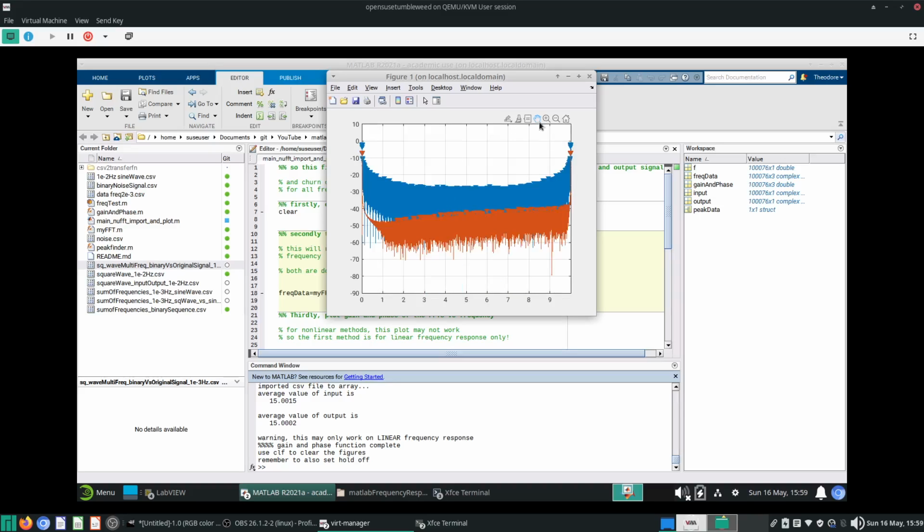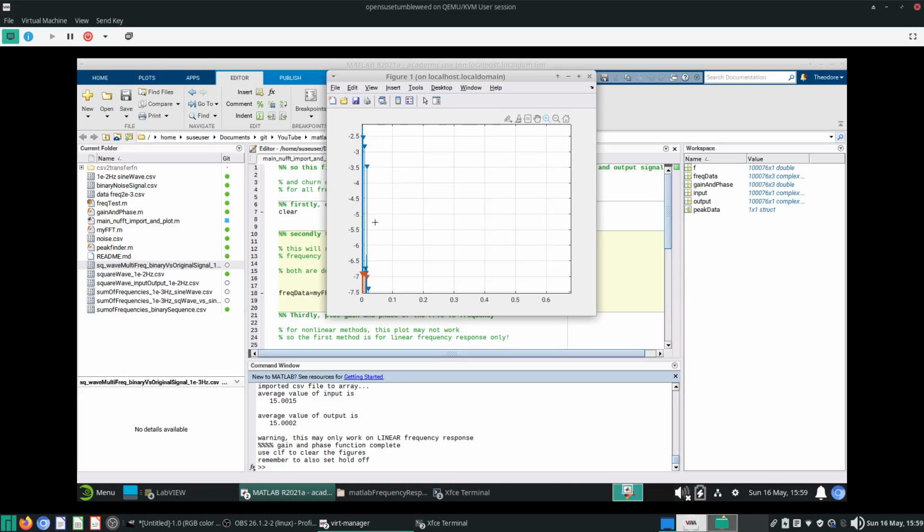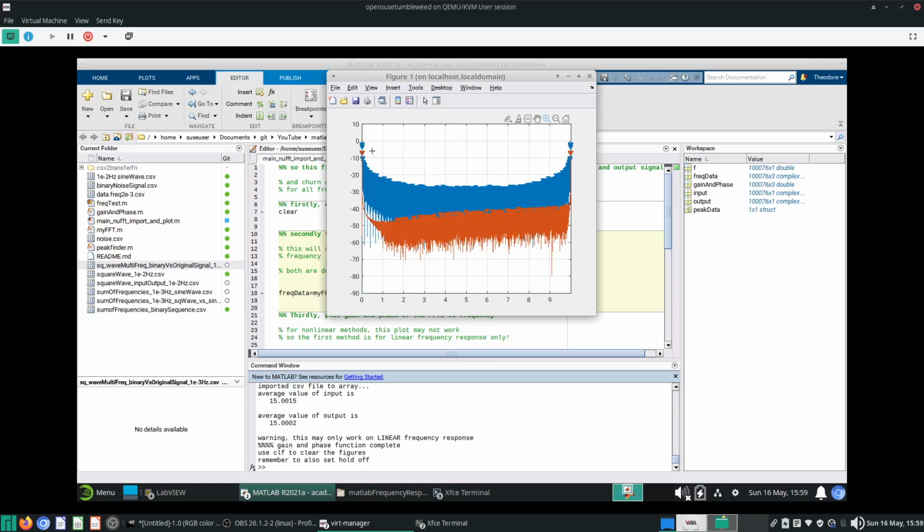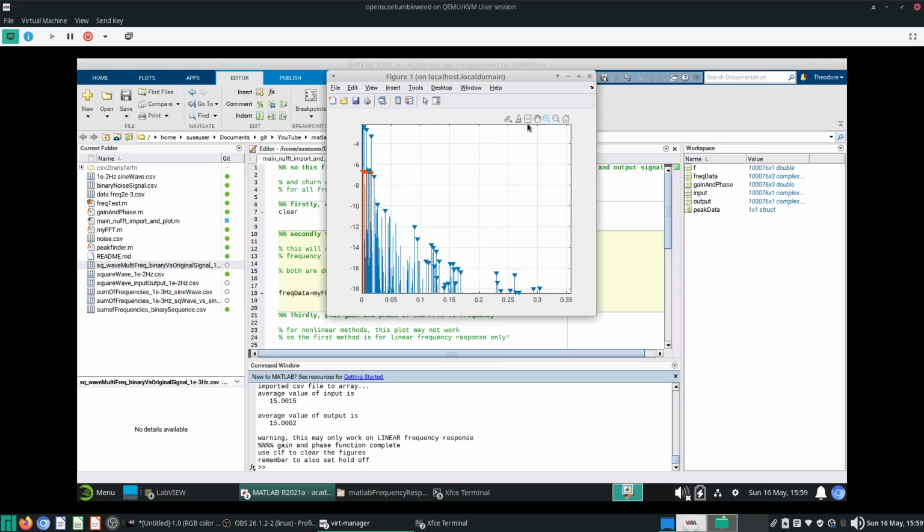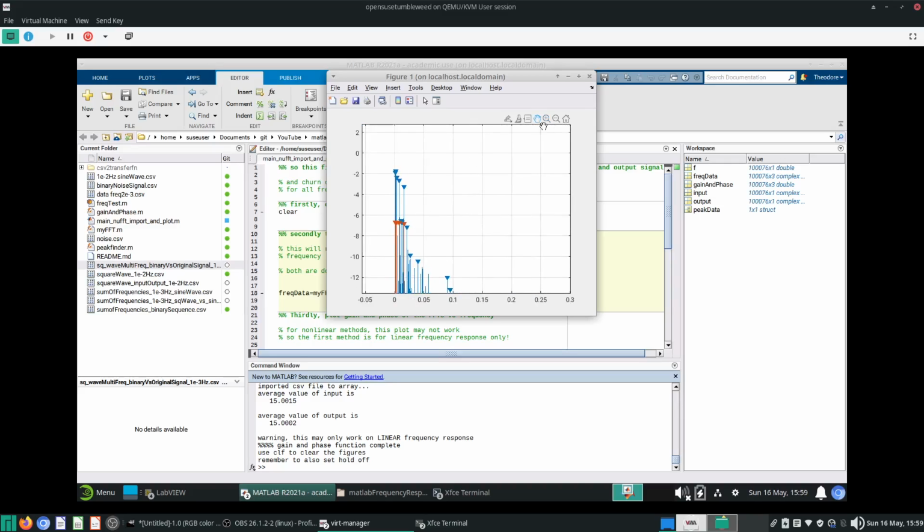Because there will always be some background noise and fluctuation at your frequencies of interest, you want to make sure that for the frequencies you're testing, your test signal is much stronger than the background noise. And for sine waves, that definitely is the best.